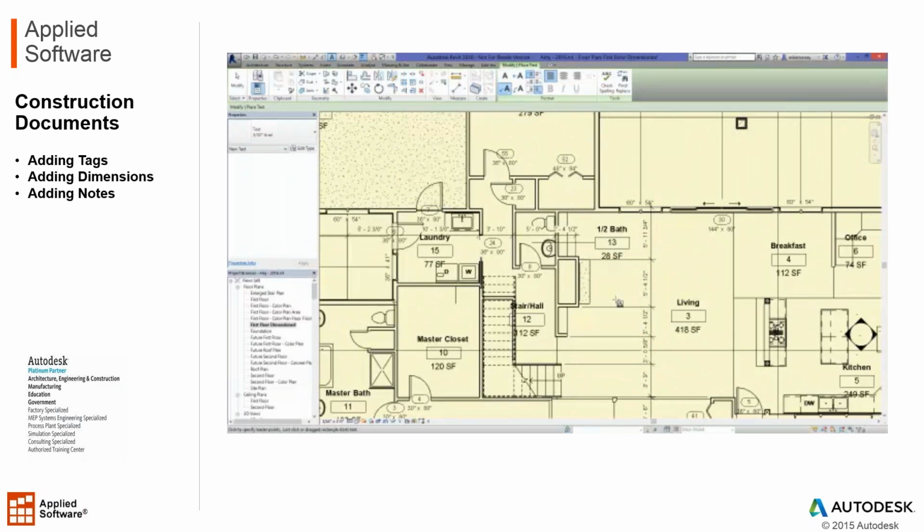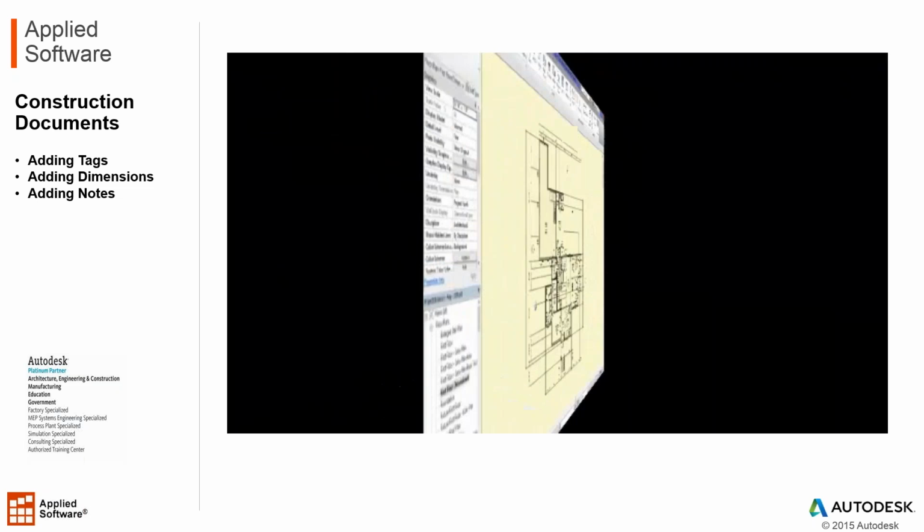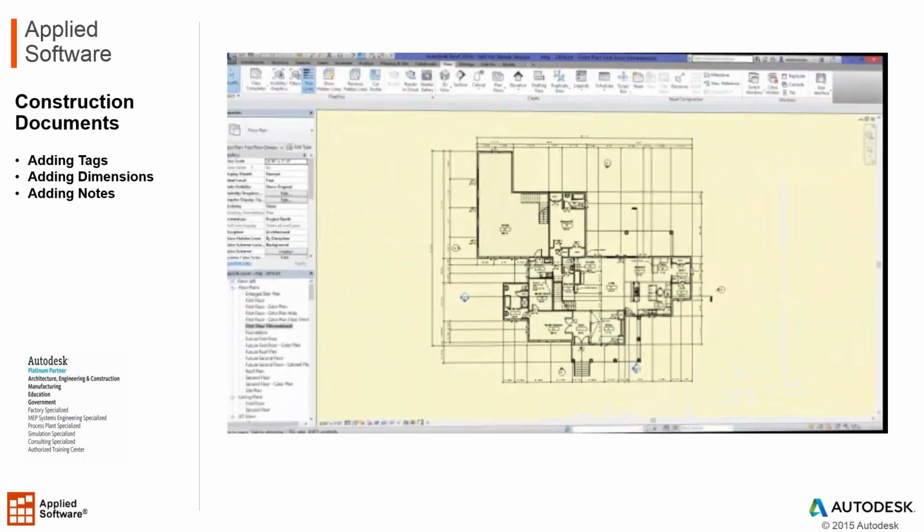You can also do text. If I want to add some notes and start manually typing out general notes and text, here I'm calling out a built-in bookcase or a built-in cabinet in my plan, and also noting that this is the fireplace. So again, just manual notes, you can do that as well. You can use tags or manual notes, whichever best fits your needs.